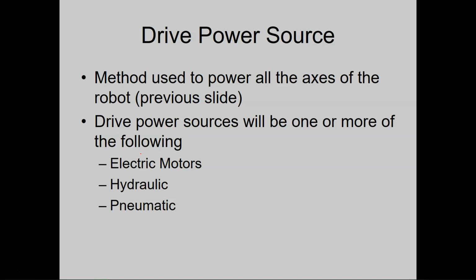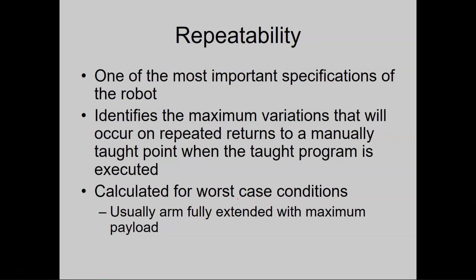Hydraulics and pneumatics are a little harder to install. Pneumatics really aren't that bad. All you have to do is run hosing from your compressor to your robot and it'll run. Hydraulic, though, you have to not only put a line out to where the robot is, but you have to give it a return line to send the fluid back. It can be really messy.